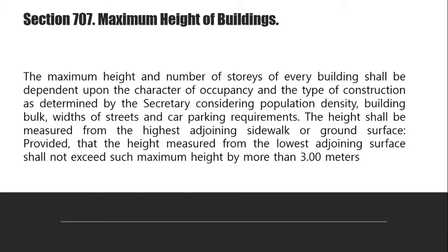measured from the highest adjoining sidewalk or ground surface, provided that the height measured from the lowest adjoining surfaces shall not exceed such minimum height by more than 3 meters, except, so this section accepts that towers, spires, and steeples erected as part of a building and not used for habitation or storage are limited to a height only by structural design if completely of incombustible materials or may extend not to exceed 6 meters.